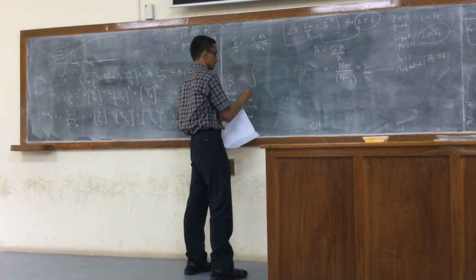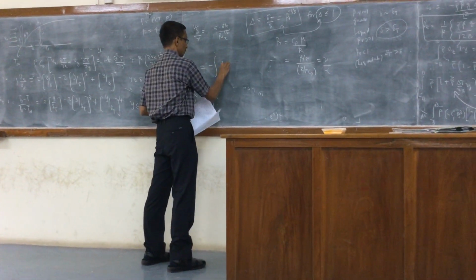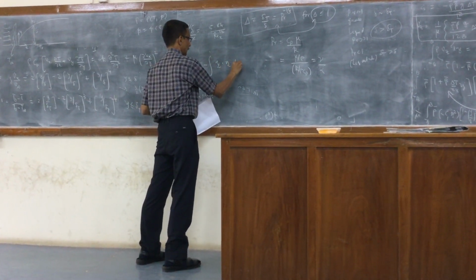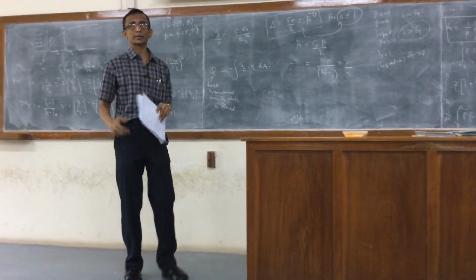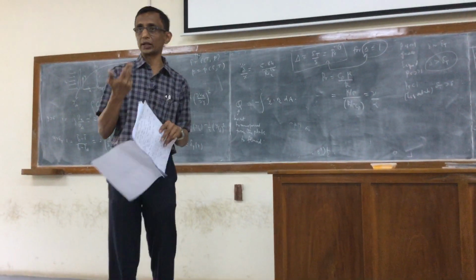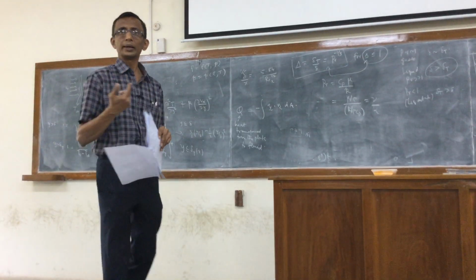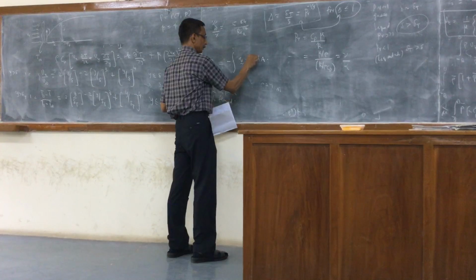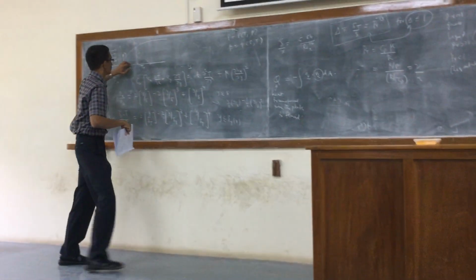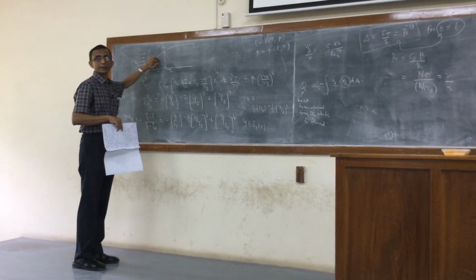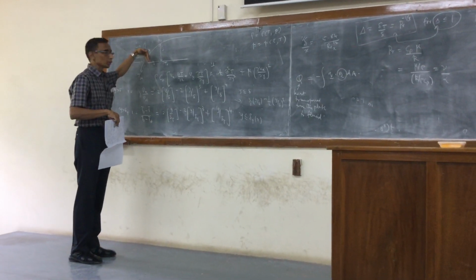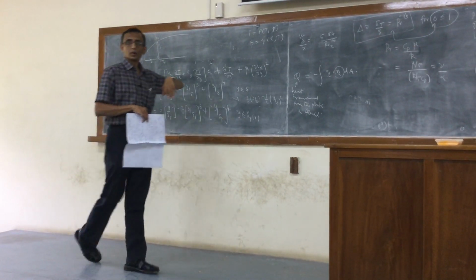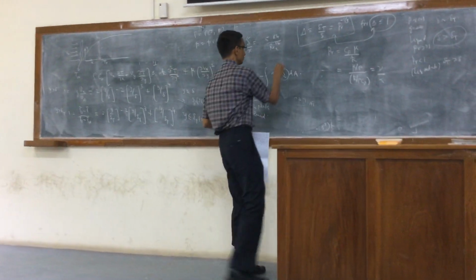That can be regarded as arising out of convection. So I can write this as the integral of minus q dot N dA. Right, so it's transferred from the plate to the fluid. Yes, it could be heat loss or a heat gain by the fluid. If you look at it as the fluid receiving heat, then the outward normal for the fluid would be in the negative y direction.